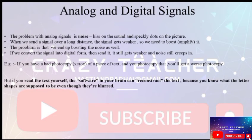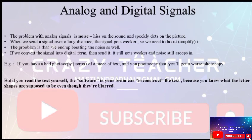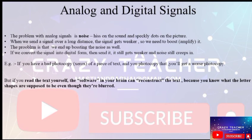But if you read the text from the page, possibly you will be able to figure out those blurrings of the different letters that you have on the page, and we can just correct it. So this is just what this digital thing does. So maybe the voltage value has reduced a bit, but it is not that much degraded, and still possibly we can figure out that this was a 1 and this was a 0. We can reconstruct the signal and then again transmit. So that way the amount of noise that got introduced may get reduced further.